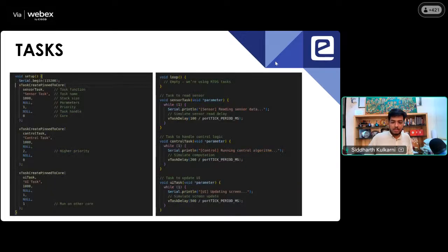Here we'll come back to the snippets again and again, but let's address this for a while. So currently during this session, we'll be talking about FreeRTOS. FreeRTOS is an open source RTOS that is Arduino compatible and you can work with it on your ESP32. So this is a simple example of the task that we need, created using FreeRTOS and Arduino IDE. If you look here in my void setup, I have these three functions. One is xTaskCreatePinnedToCore. That is, I'm creating a task and pinning it to a core. ESP32 has cores, and this is a function that allows me to create a task.